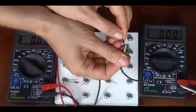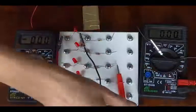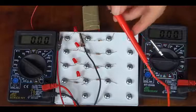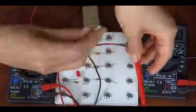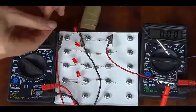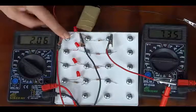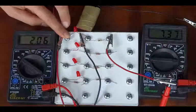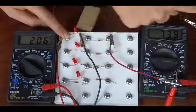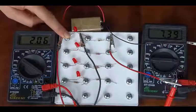I'm just going to connect it straight to the negative terminal of the battery. And then the positive terminal of the ammeter needs to complete the circuit. And I'm going to use a crocodile clip. I'm going to connect it there. So as soon as we then connect the positive terminal of the battery over here, we will have a complete circuit. So notice we have a complete circuit from the positive terminal of the battery through the LED. The current flows through the resistor and then through the ammeter and then around back into the battery, negative terminal of the battery. And we have our two readings.